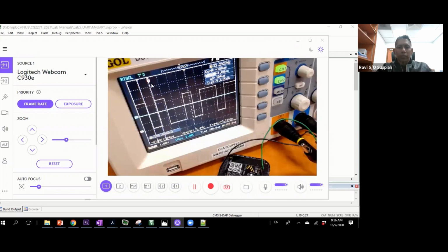Okay, so the first bit is your which bit? This low is which one? Okay, yes, correct. The low is the start bit. Okay, so if you look back at your UART documentation, all right, in the slides, you will see that the idle line is high, and when a transmitter wants to transmit, it will pull the line low.